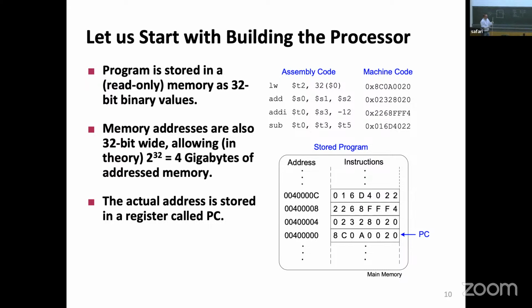Now, I know that 2 of my operands are coming from this 32-bit register file, and I know that this is the first address that goes here. So one part of this wire, not all of it, which ones? The ones from 25 to 21. If you say this is the instruction, so the instruction bits 25 to 21 will connect to this first address. There's a nice figure in the book, don't worry, don't try to draw this. And the second one is going to be the next bits, instruction 20 to 16.